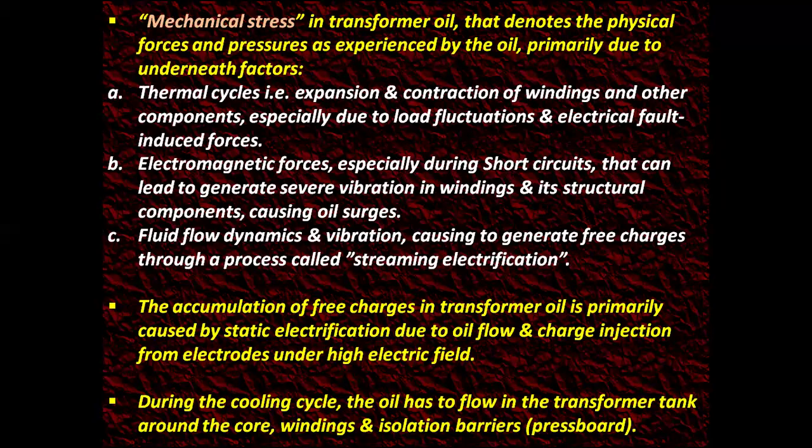The accumulation of free charges in transformer oil is primarily caused by static electrification due to oil flow and charge injection from electrodes under high electric field.